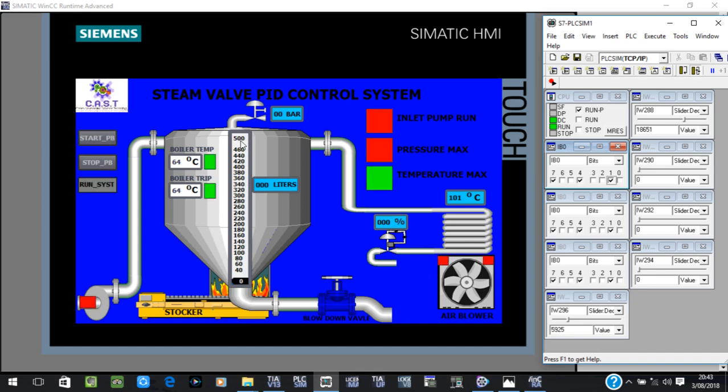After this, the valve is closed. It's in manual mode. It's 0% opening. Our stoker here in yellow, if you activate it, it has to push the burning coal into the furnace or the combustion chamber rather to heat up the water. So as we heat up the water, we will have an increase in temperature and also an increase in pressure as we start to produce steam.